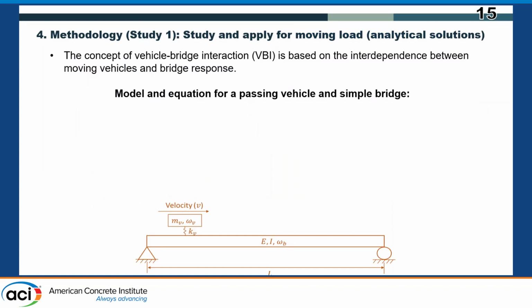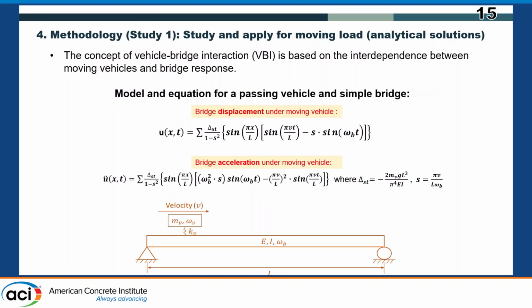After we develop our FE model, we need to verify it with an analytical solution or testing. First, I want to introduce the vehicle bridge interaction equations. By using these 2 equations, we can calculate the bridge displacement and bridge acceleration under a moving vehicle. So we can easily find these 2 values at a certain time with a certain vehicle location.